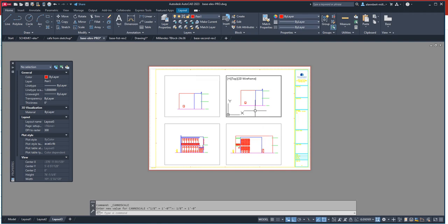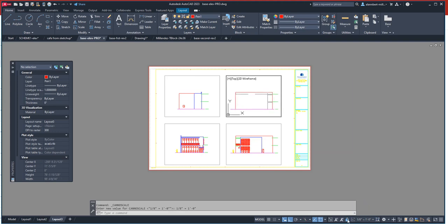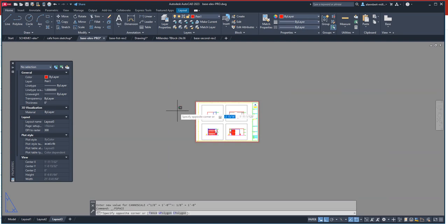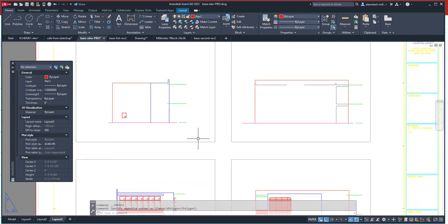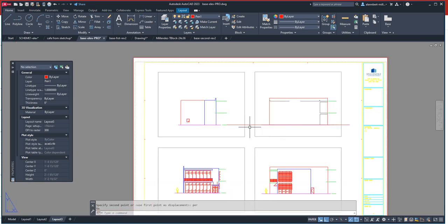And then over here, the same thing, but we're going to show the right elevation. Let's make sure that it's at 1/8 and then lock it. Okay, and when you're making these elevations, we have to make sure that all of their levels, floor to floor, are all level. So in paper space, make sure you double click on the white, not on the gray area. Okay, let's draw a line temporarily so that we know how to level them up. So we're going to just move the viewport and hold it from that elevation line and make it level with that temporary line.